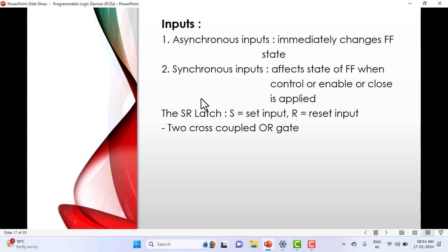Prior to the rising edge coming in the clock, we expect that J and K, for some duration before that rising edge, must be 0 or 1. But also ensure that you must not change your data when the rising edge comes. These are the timings I'm telling once again. We say setup time and hold time, right?